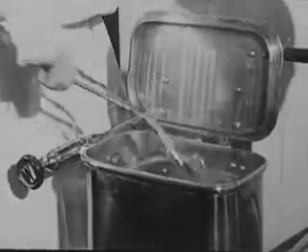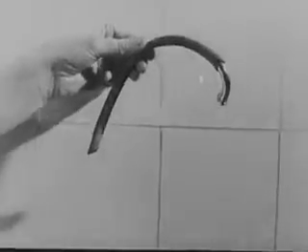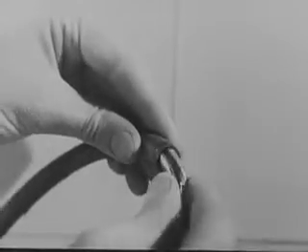One word of warning, however. Here is a tube that has been boiled with a metal connection attached, a thing that should never be allowed to happen. You can see that the end of the tube is now permanently stretched. It is therefore unsafe to use it.